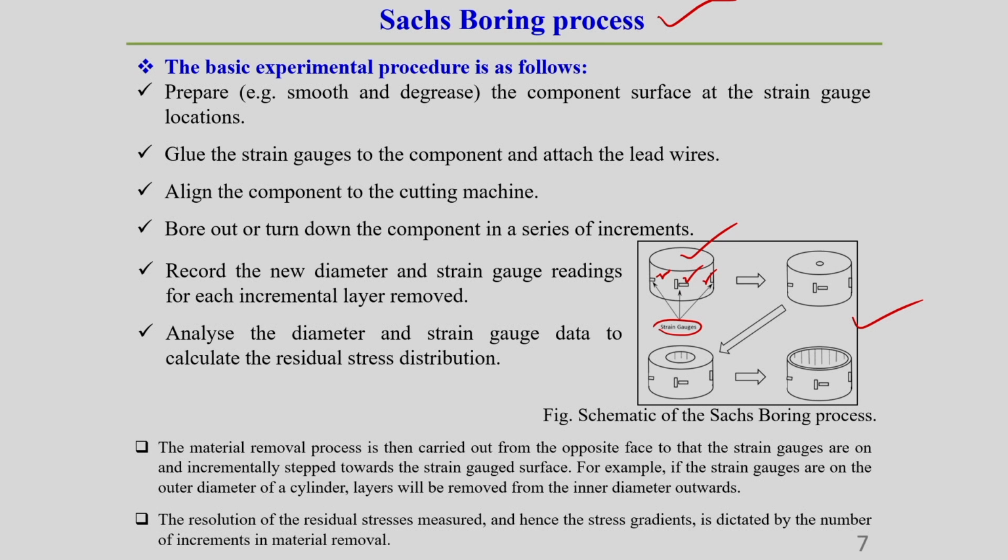There should not be any dust or grease, because if there is any dust or other things, your strain gauge reading will be wrong.